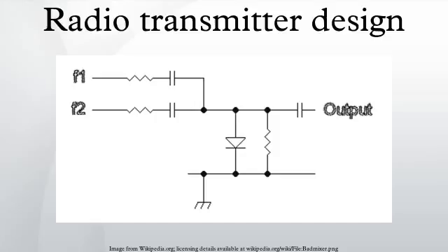While it is perfectly possible to create good designs using solid-state electronics, valved circuits are shown here. In general, valves are able to easily yield RF powers far in excess of what can be achieved using solid-state. Most high-power broadcast stations below 3 MHz use solid-state circuits, but higher power stations above 3 MHz still use valves.